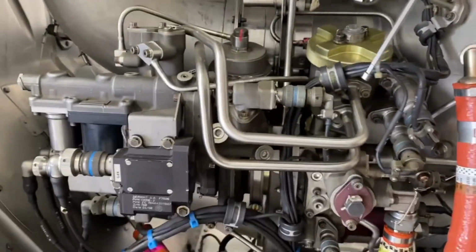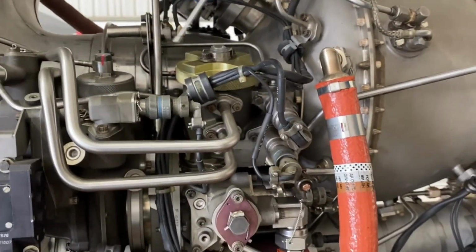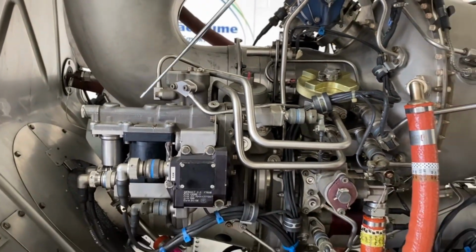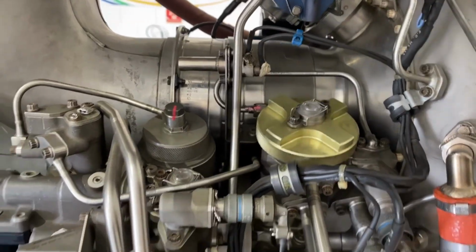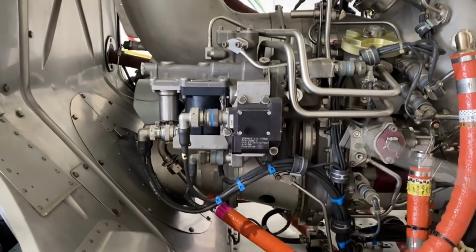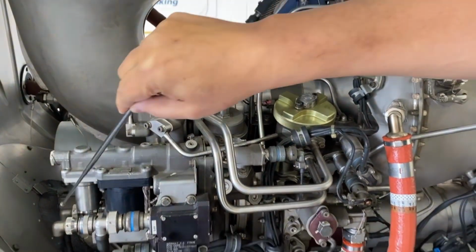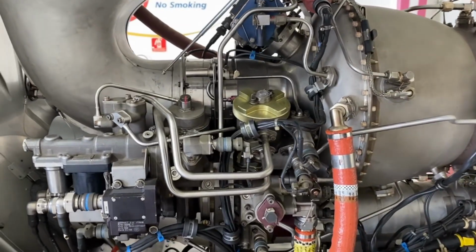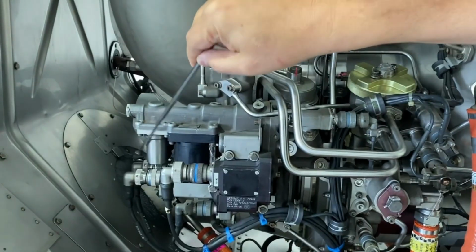It is heated here in a heat exchanger with the oil system. The oil is hot, and then it returns back to the HMU. Before the fuel enters the needle for metering, it passes through a fuel filter. So this whole block, the low pressure pump, the high pressure pump, the filter block, right? The metering needle, the stepper motor, the helical, all of that is part of the HMU assembly, okay? And this control here, as I mentioned before, is managed by both channels of the FADEC.